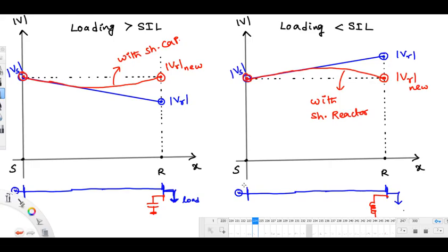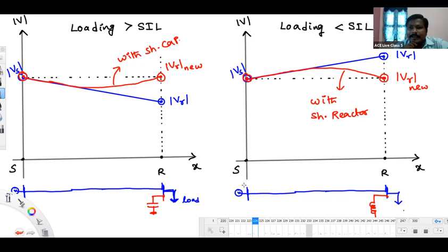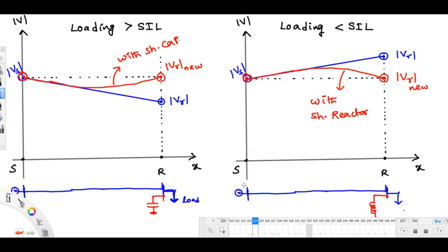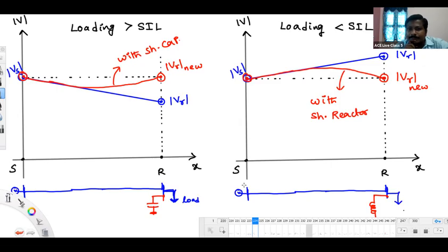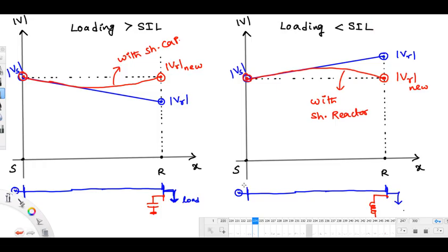But if we calculate the same delta using the equation Vs equals A VR plus B IR, I am getting a different value of delta. How did you get the IR value there? The IR values are given for the load. That is the load current, not the receiving end current of the line. The receiving end current will be different because of the charging current, since the capacitor is added. Exactly, it is not the load current. Because of this, we are getting a different value.